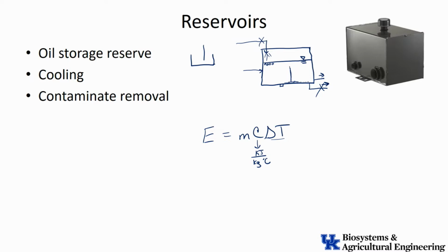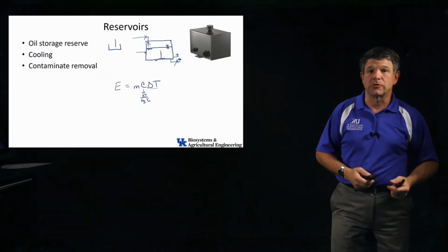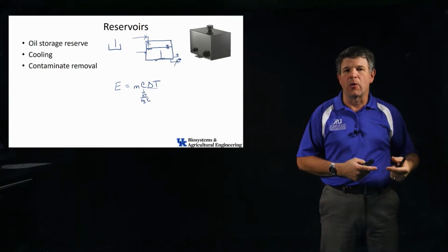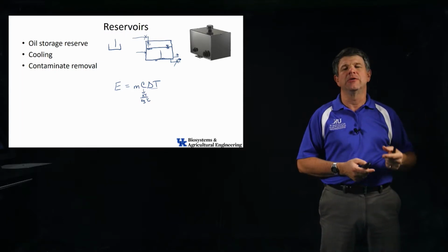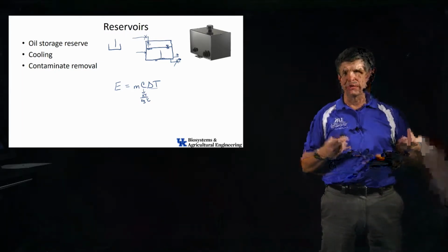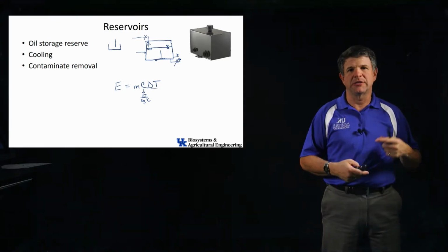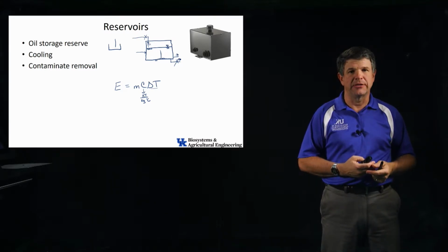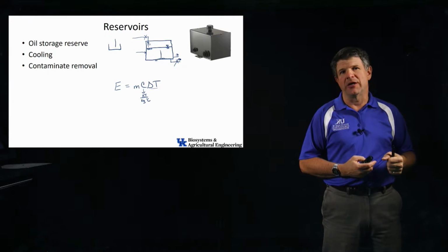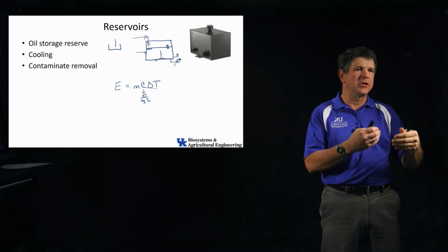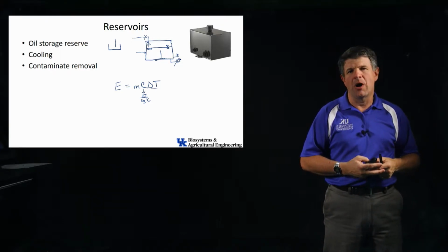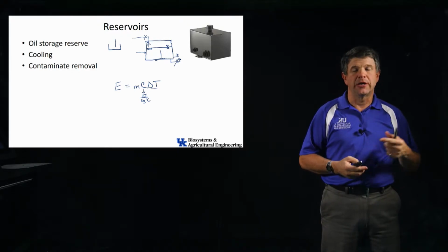And by the way, an interesting thought about reservoirs: if you look at an agricultural tractor, the reservoir is the transmission. The oil that lubricates the gears is the same fluid that we use in the hydraulics, so we have one big reservoir. It is actually multifunctional. It provides the lubrication and the cooling for the transmission, and in fact a lot of our transmissions now are hydraulically activated, so they're not old school shifting and grinding gears. They're using switches and levers, and it's all hydraulically activated with clutches and things like that. So there's a lot going on in modern mobile machinery, and that transmission is also part of it.